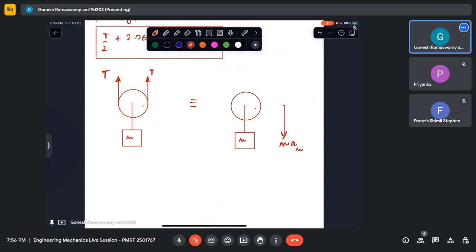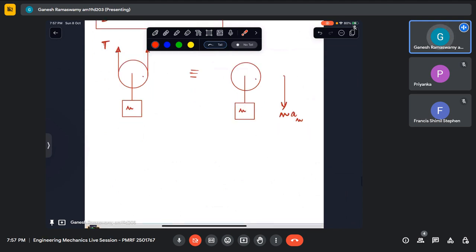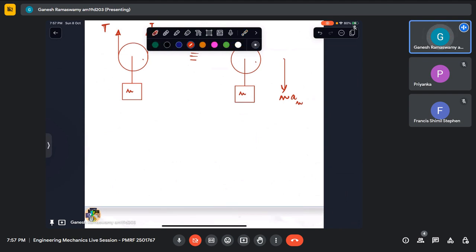So this is having rectilinear motion. It is easy to see that this is just undergoing rectilinear translation, nothing else. So there is only one thing appearing in its equations of motion. So can we add this up? What will this be? It will give me 2T minus mg is equal to minus m a of the mass.